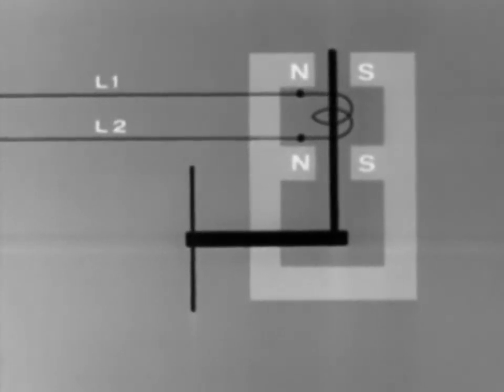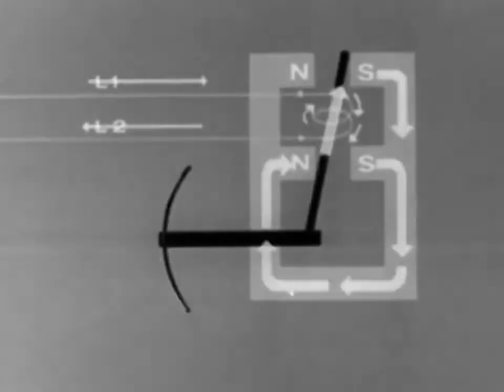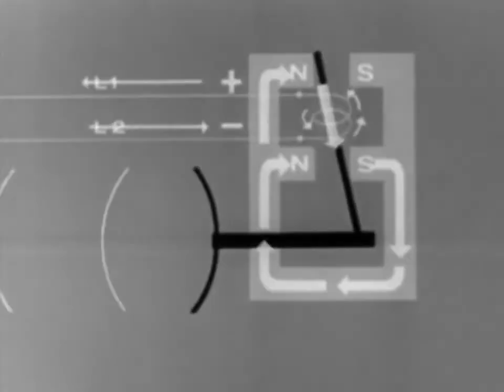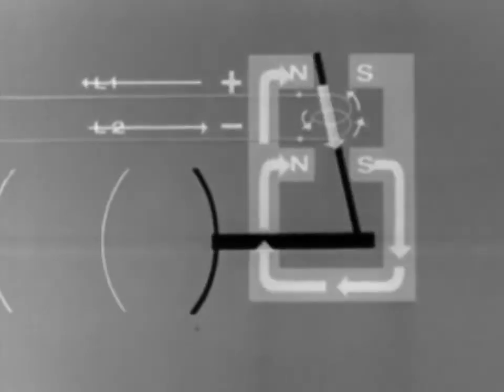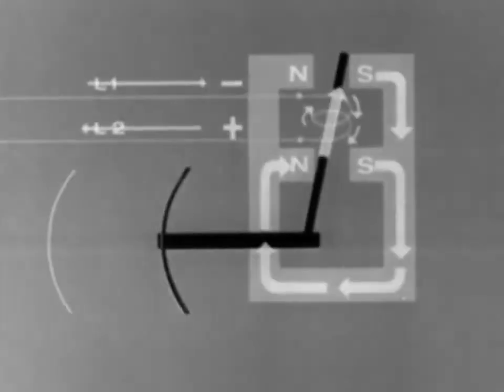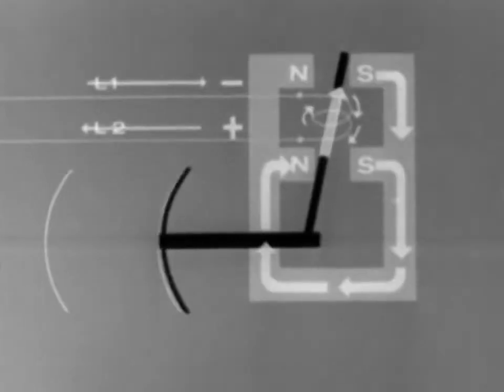As the voice current in the coil alternates, the polarity of the armature reverses, causing each end to be alternately attracted or repelled by the permanent field magnet. Consequently, the diaphragm pushes out audible sound waves exactly mirroring the waves of the original sound.